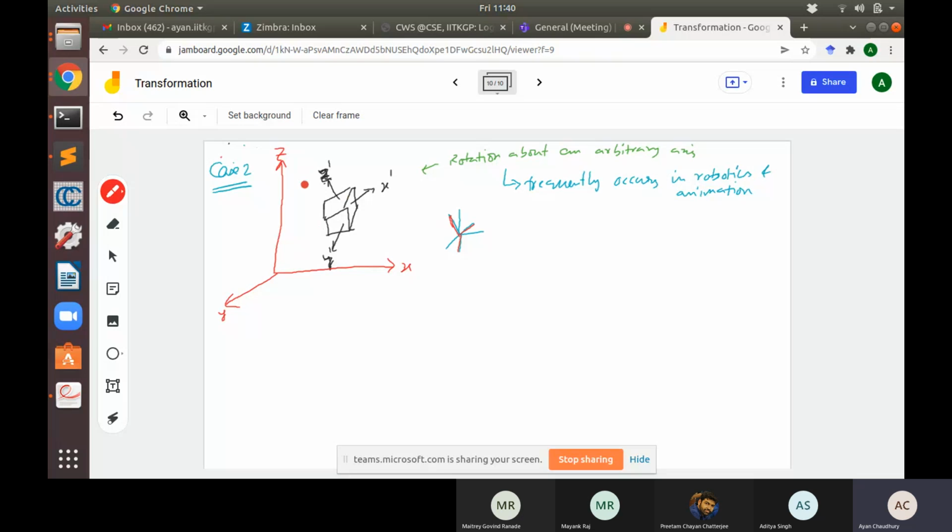Yes, actually, let's say we try to rotate around the z axis. What we have to do is make this local z prime axis coincident with the z axis. But the problem is that this is in 3D, not in 2D. So think about how complicated the case is. We have to do other types of rotations just to coincide z prime with z, right? Because if you try to rotate z prime to z in 3D, it's not possible since you don't know this angle. So that means you have to do two transformations, actually two rotations.